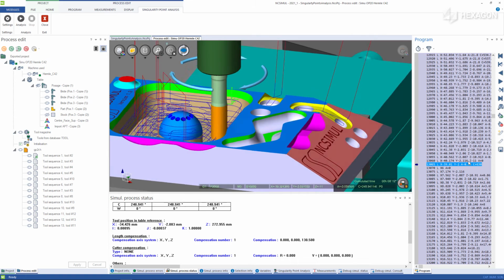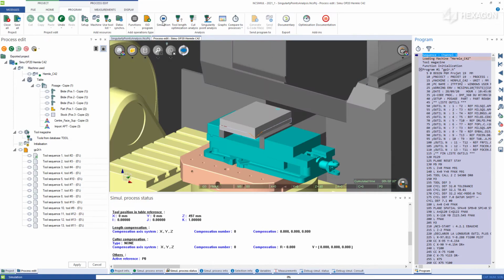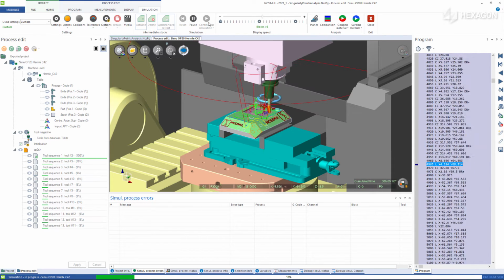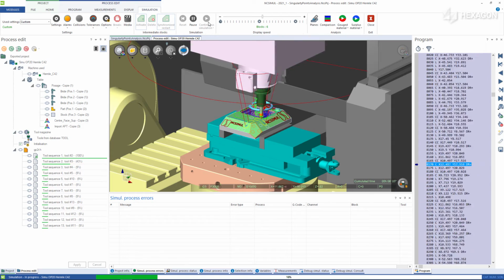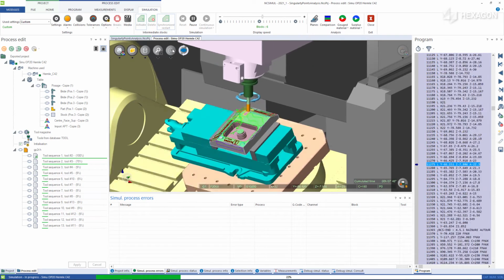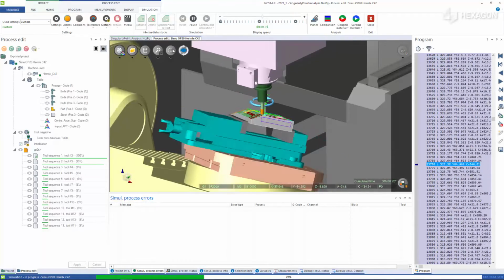All of this can be used to find the best possible setup point for the part on the machine table, limiting the distance to the pivot center of the axis, and finding the best orientation to decrease the number of singularity points. By doing this, the number of jerk moves will decrease, increasing the quality of machine surfaces, tool life will improve, and the final product will more consistently reflect the program tolerances.